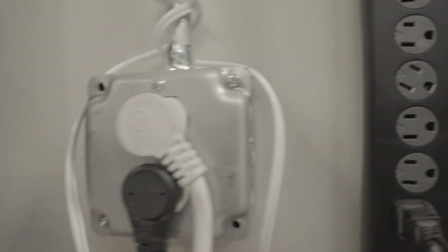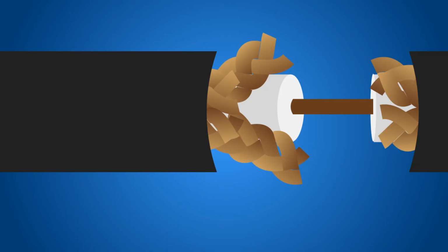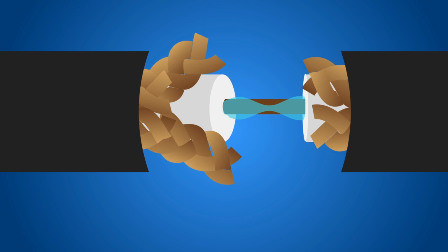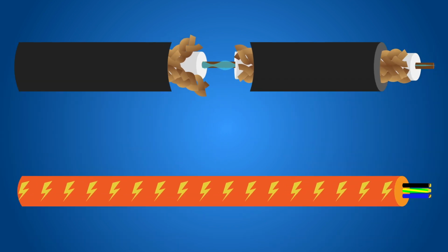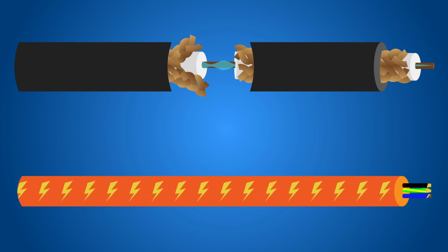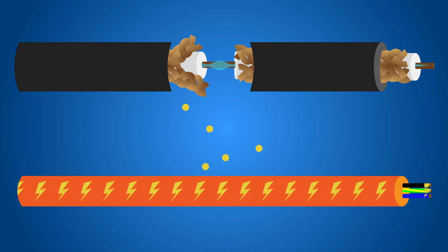So as you saw, I took the cable, I ran it out into our warehouse, I wrapped it around that outlet a couple of times, it was kind of braided around our power cords, and then I brought it back into this room to power up the camera. The problem with that is, since I was using poor quality cables, having these cables in such close contact to these power cords introduced a ton of electrical interference.